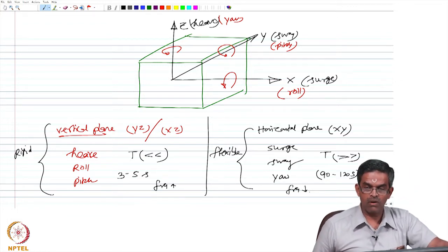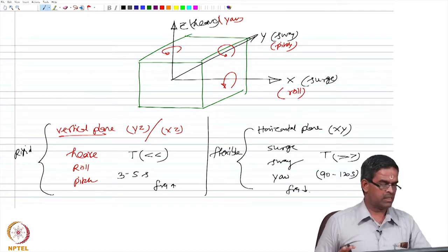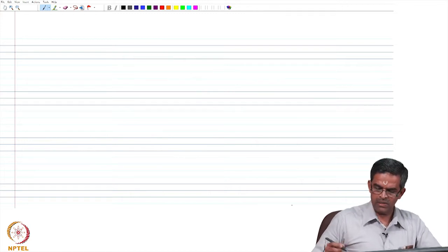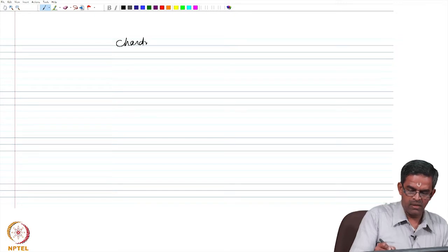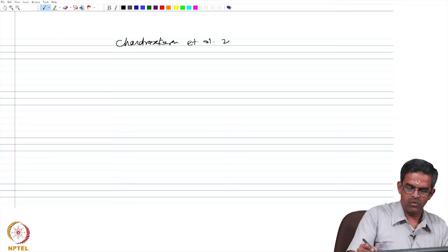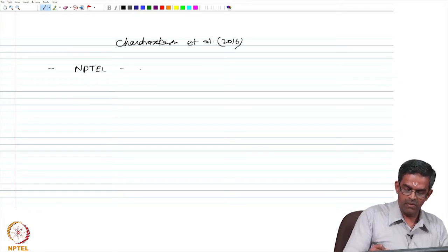Okay. So, we are talking about two distinct sets of frequencies which are to be measured and then compared for damage detection, which is done using postulated failure. That is the idea here. More details of this structural model can be seen at Chandrasekharan et al., 2016. There are more interesting NPTEL lectures which have discussed offshore structures,